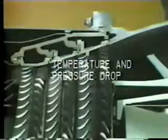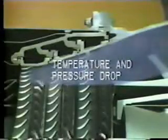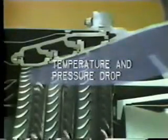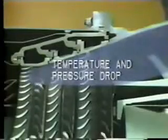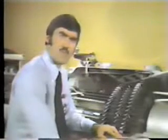An impulse of air striking the leading edge of the rotor blade, and expanding air reacting against the blade's trailing edge. Both ways together maintain the evenness of the turbine's rotation at operating speeds. The expanding gases drop in temperature and pressure as they drive the turbine. The gases then exit through the turbine exhaust diffuser to atmosphere.